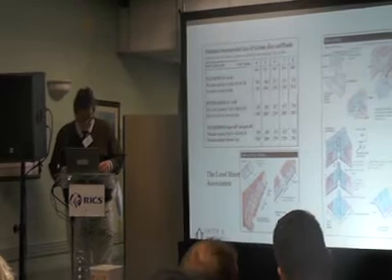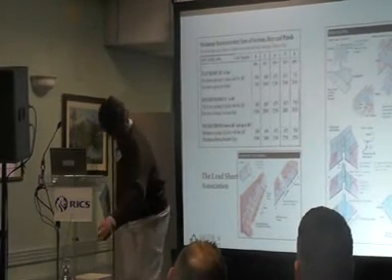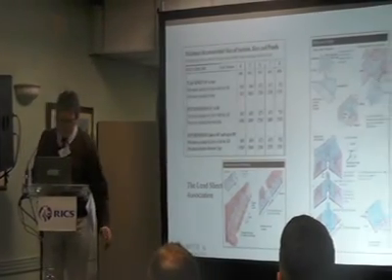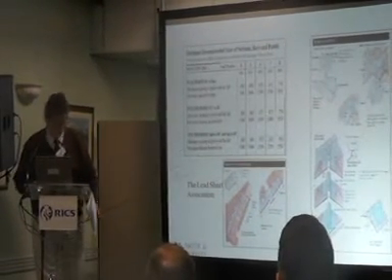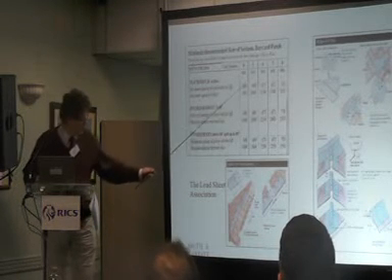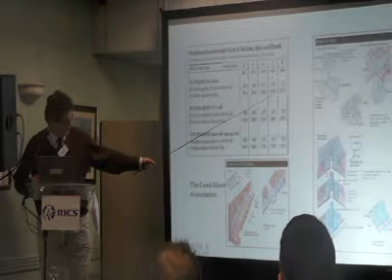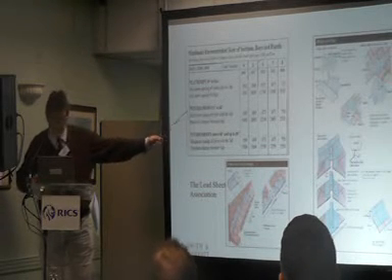And the top left table, what's really important about this is it sets out for you the bay length you need before a step when you're using code 6, code 7, code 8 lead. 2¼ meters before you have a step, 2½ meters before you have a step, and if you need a 3 meter bay, you've got to make it in code 8 lead.